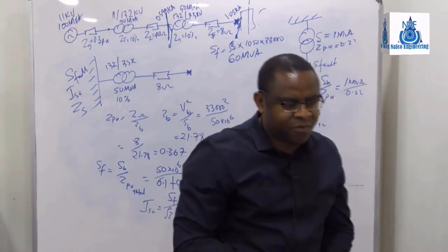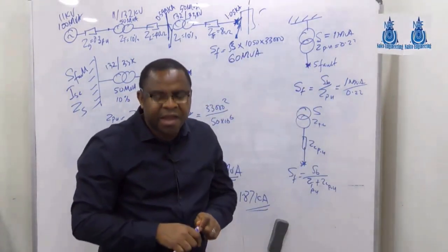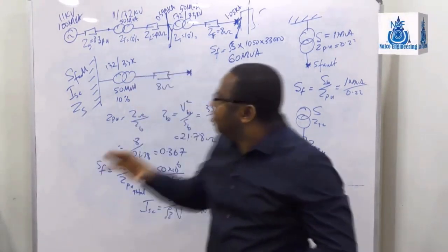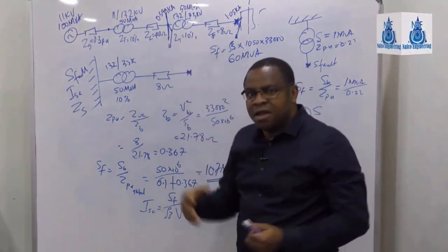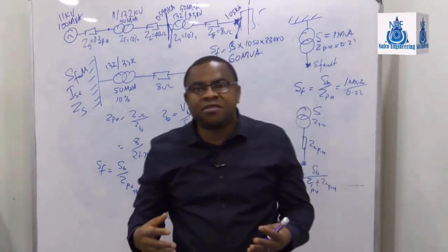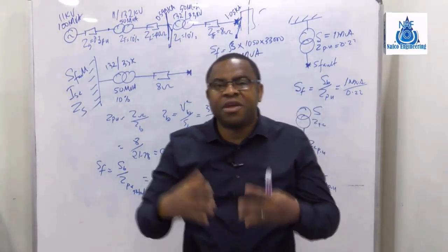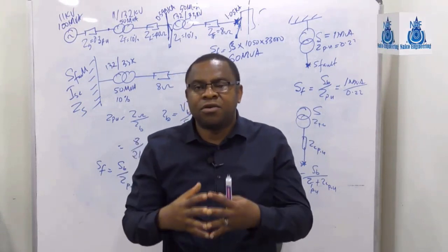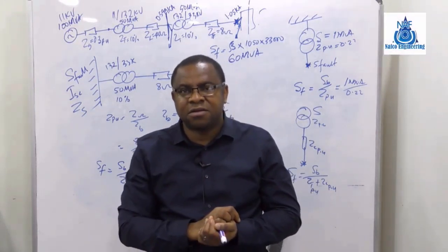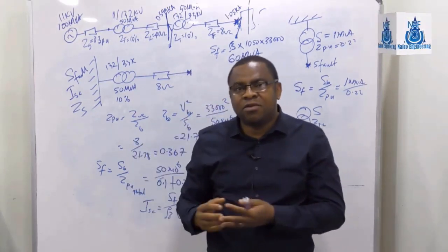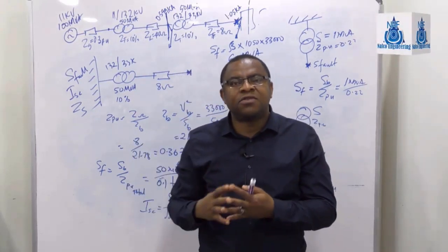So let's just finish up this so that we'll be able to solve problems. Now, remember, when you have a switch gear here, or a switch gear there, a switch gear contains bus bars. Even so, all the bus bars should be able to handle that fault level. The strength of your bus bar should be able to handle the prospective short circuit current.